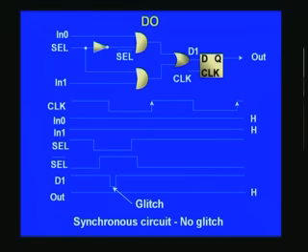Another thing we talked of earlier is the glitch, which is an unwanted, uninvited guest that you would like to eliminate. For example, this circuit gives a glitch as far as this combinational circuit is concerned, and a narrow pulse like this is known as a glitch. How it is produced, we will just have a look. These are all plain AND gates here with an inverter here, and then finally these two are ORed and applied to a D flip flop.